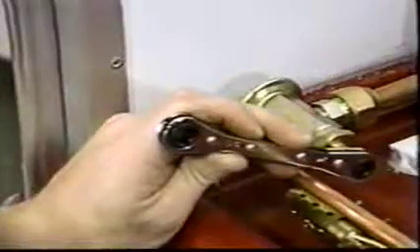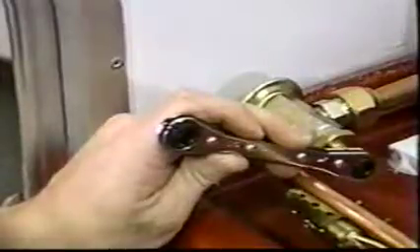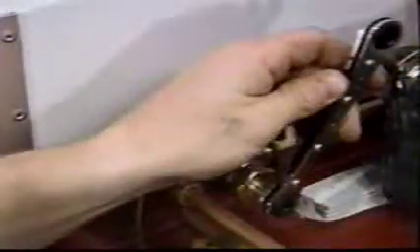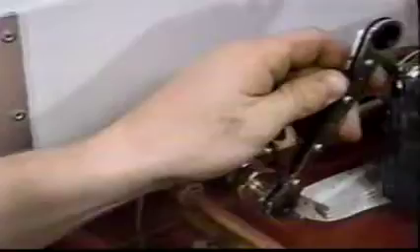If adjustment is necessary, the superheat adjustment screw is turned 1/4 of a turn at a time until the system operates with the desired superheat at the evaporator outlet. Again, be certain the system stabilizes after each adjustment to assure balanced operation. Double check that you have properly set a superheat level that will work well under all operating conditions the system will see.